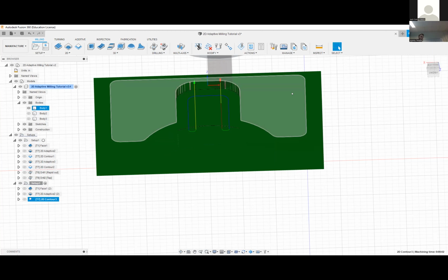If you had like a part that had an internal path, because that's not like a linear path, would you be able to machine that? No, that's a 3D printing issue. So you're talking about like a fluid channel that's curving. Yeah, okay. So you'll want to 3D print that, or you can sometimes have intersecting drill holes. So if I drill this way and drill that way, they'll hit each other, but that gets me 2 angles and that's it. So those are 3D printed parts and they're beyond the realm of traditional machining.